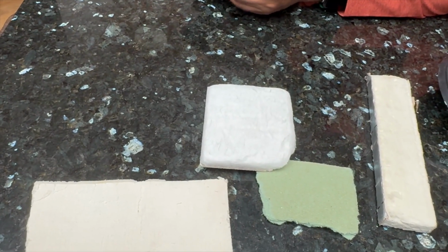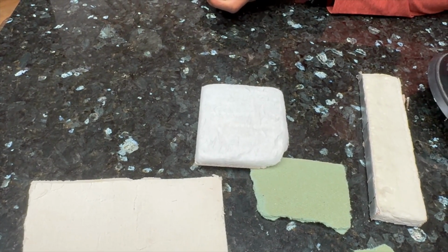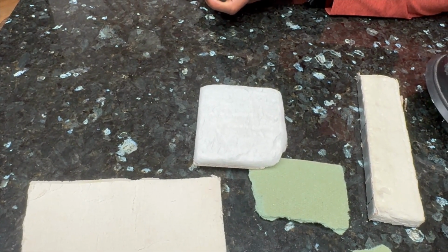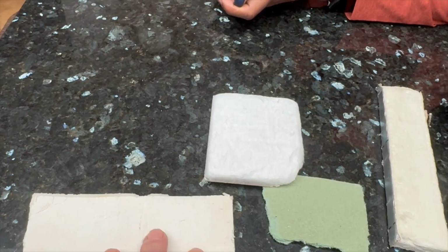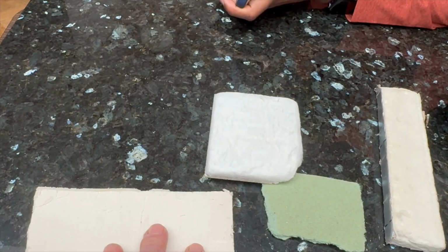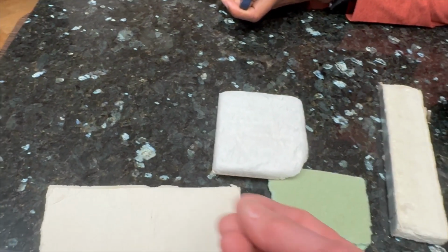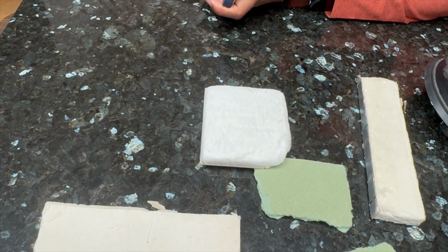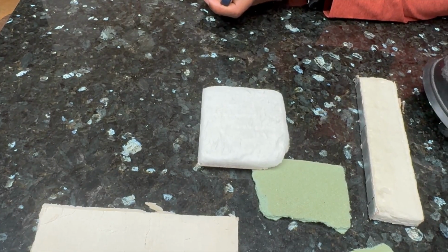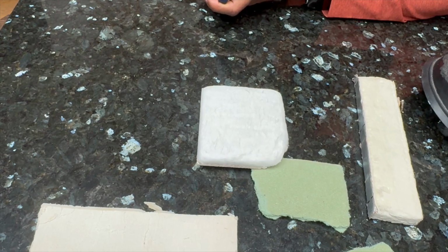I mean, as much as anything else, you're never going to get those walls looking great, especially with the lintel where the plaster is blown. So putting lining paper is going to go a long way to solving that, and it will give it another 2 or 3 degrees centigrade, which would be enough to take it from being a mold risk to normal.